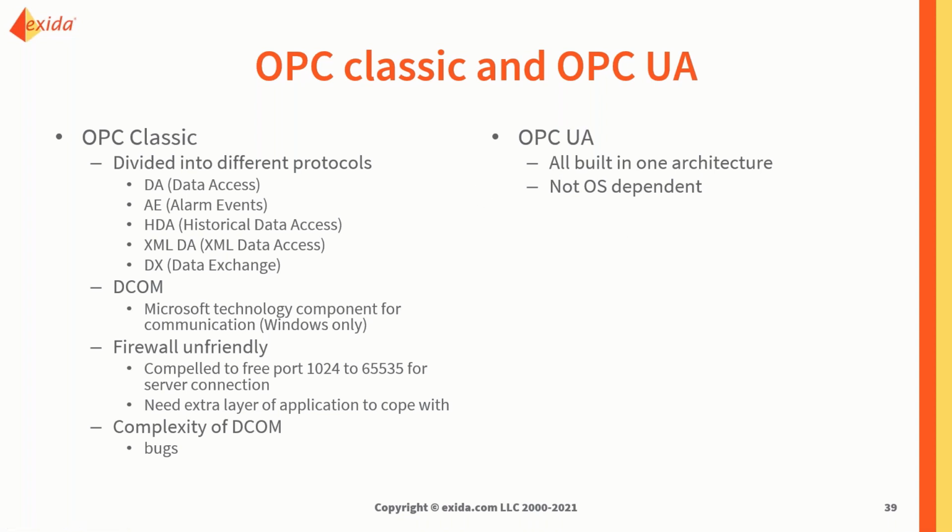And also OPC UA has all this information and requirements on functional safety, alarm management, and also cybersecurity, like security control and security layers. That's why we need to use OPC UA, the most updated version of OPC, in order to have better and safer operations.